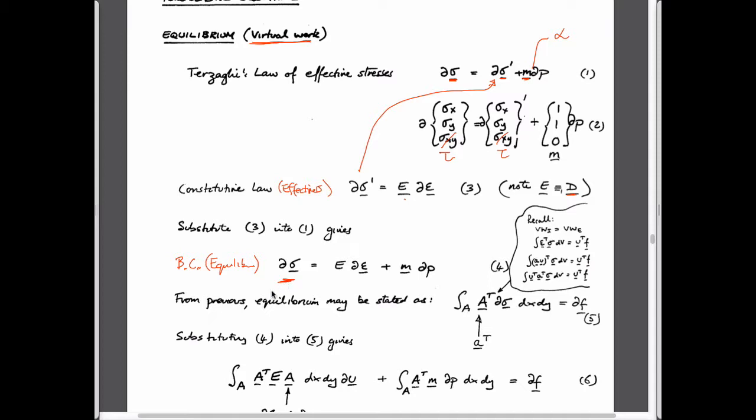It's the same as this, right? If I wanted to look at equilibrium of this, the forces acting down on it and upwards have to be in balance. But these are total stresses that are applied. It doesn't matter what's going on in terms of fluid pressures and intergranular stresses inside there. That would condition whether it gets shorter or longer because of compression, but it wouldn't affect equilibrium. We're cutting out the system to be able to look at that. And so now that we have our effective stress law written in terms of strains, we realize that our virtual work statement is also written in terms of total stresses.